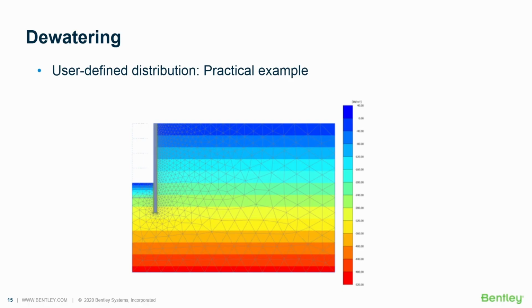And then finally, what you will observe usually is, as I said, no flow will really take place. You will just have piecewise hydrostatic distribution, where you see that the phreatic level and the piezometric line remain parallel to the defined reference water level.